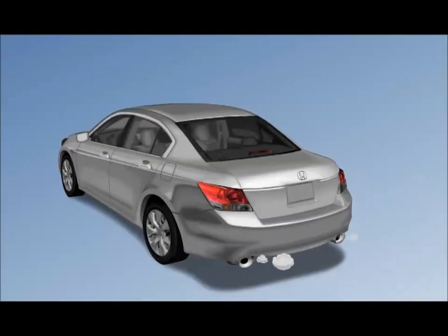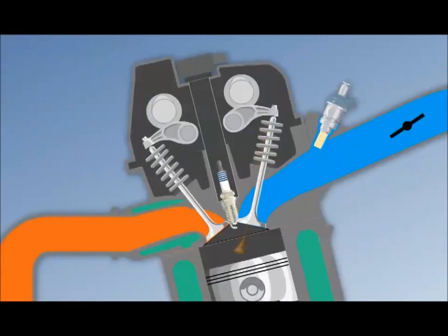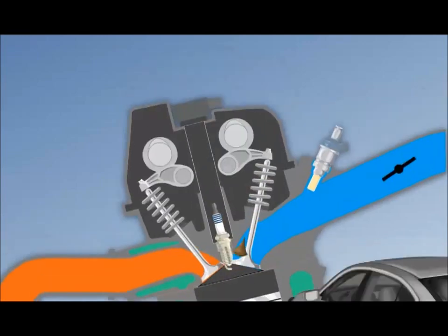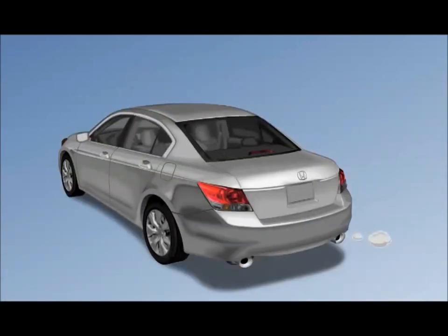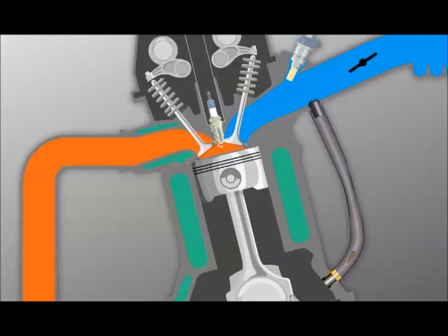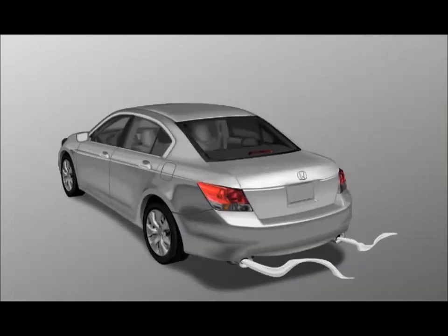A vehicle that produces oil smoke at engine startup has oil dripping onto the intake valve through the valve guides. A small pool of oil accumulates on the intake valve and creates a puff of smoke at startup. As the valve stem seals and valve guides degrade further, they begin allowing oil into the combustion chamber during high vacuum conditions. If these checks find a problem, replace the oil and look again for white smoke with the engine running.